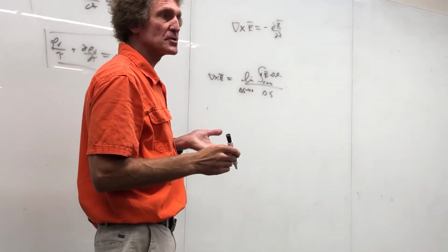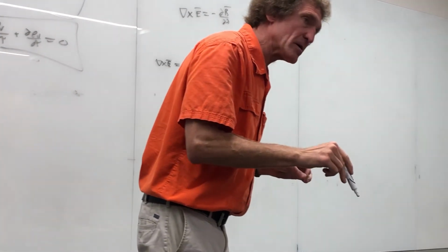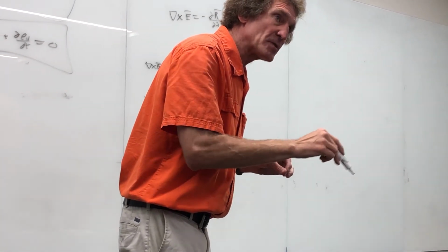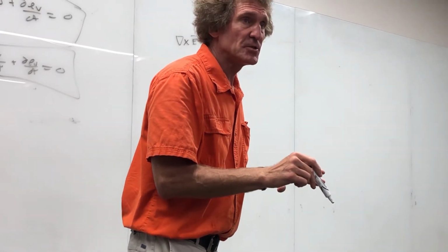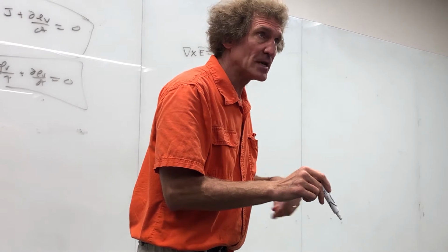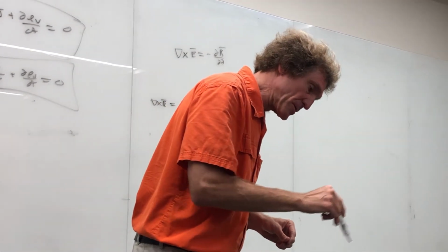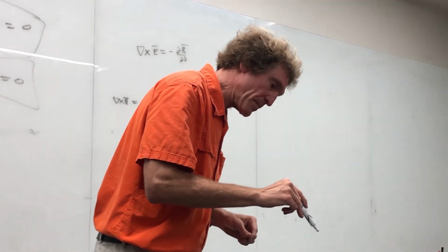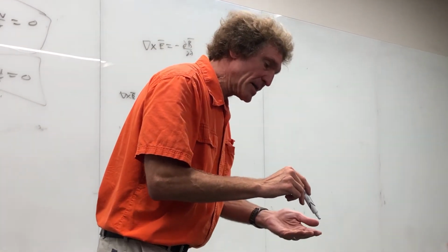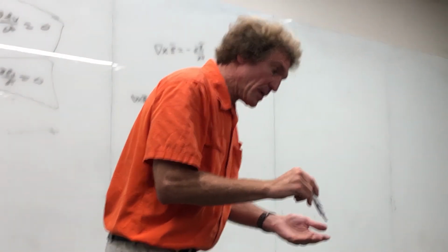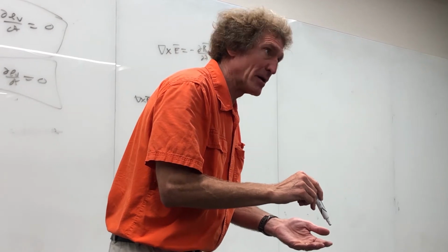But what it amounts to is if you think about E dot dl and integrating around a closed circle, really it's almost like a voltage, but you know it's not electrostatic voltage. This has to do with the time-varying magnetic field inducing a voltage, transformer action. So if you think about a total voltage around a length of wire, whatever that is, and you divide it by the area, it's kind of a weird unit system. It's voltage divided by area, right?